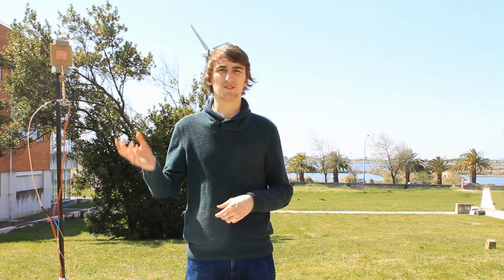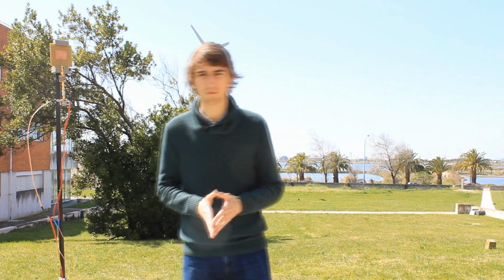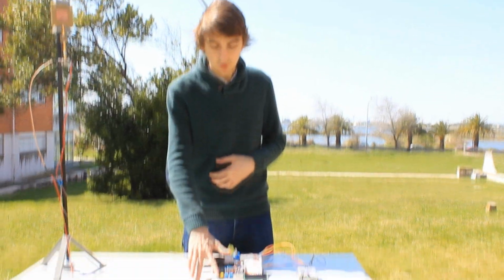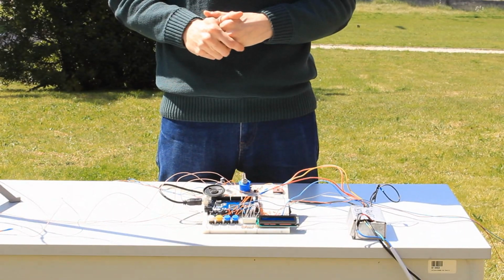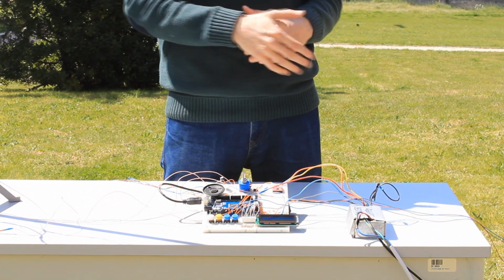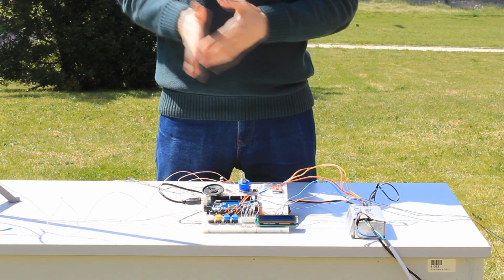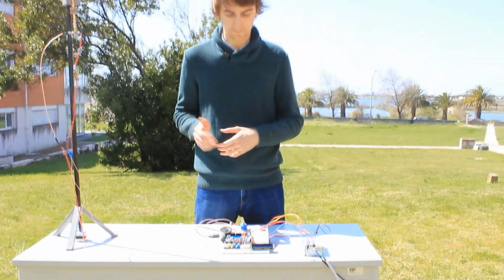The main component of the central unit is a microcontroller. It is responsible not only to process all the data received by the antenna circuitry, but also to provide a user interface. Focusing on that user interface, and starting from the inputs, we can see one push button to calibrate the whole system, one push button to sweep through all LCD stages, and two push buttons so that the user can rotate the transmitter antenna manually.